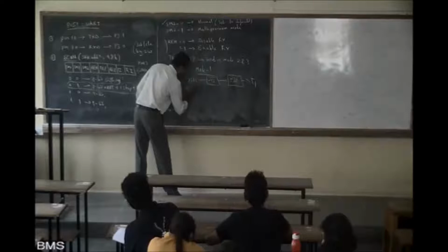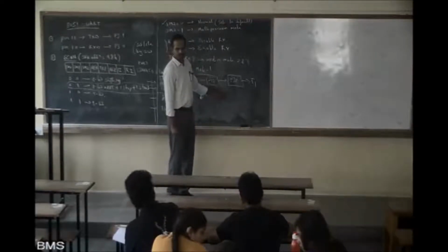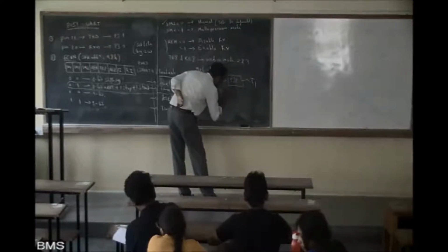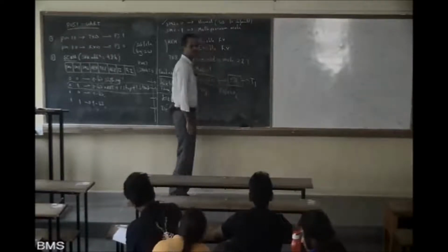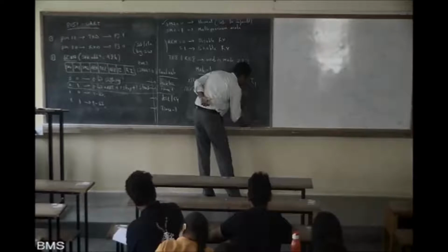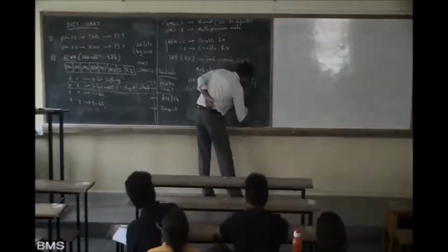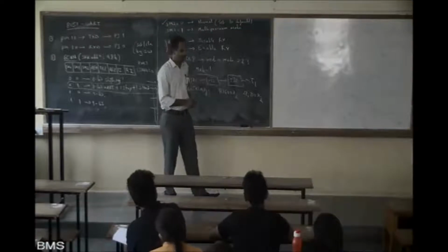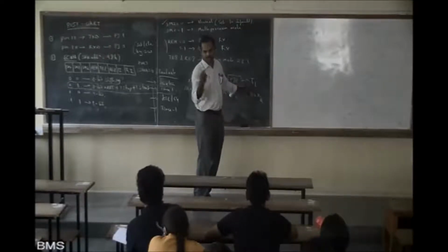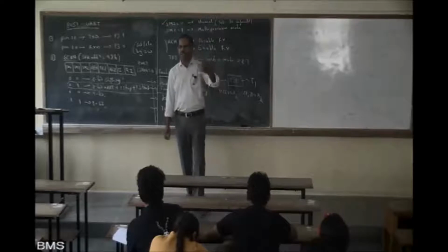What will be the frequency at T1 if it is 11.0592 megahertz? Divided by 12, that is 921600 hertz. Divided by 32, that is 28,800 hertz. Correct, right? Guys, listen. This is the one which decides the timer 1 increment rate, with what speed your timer counts.